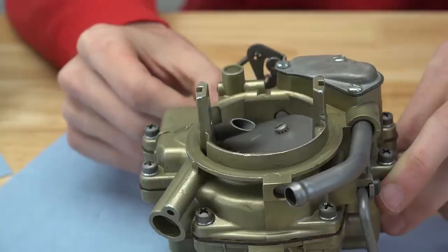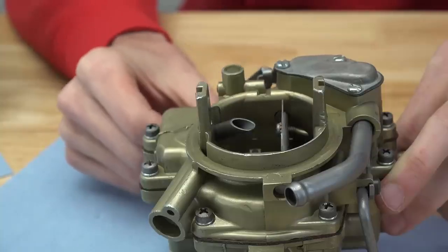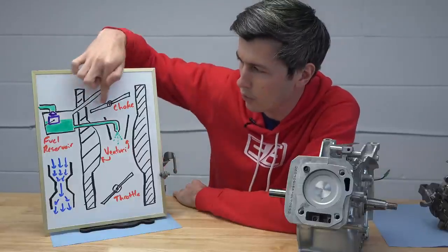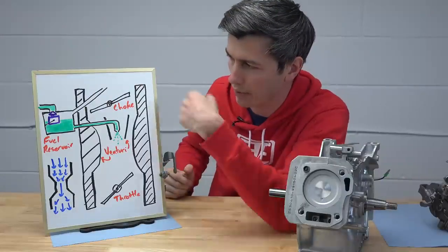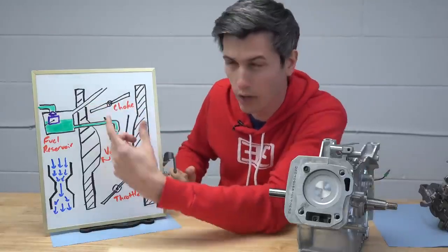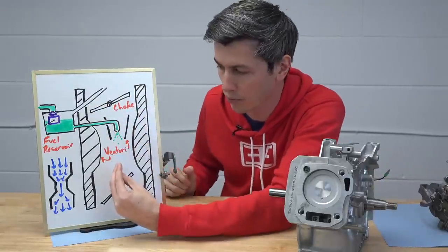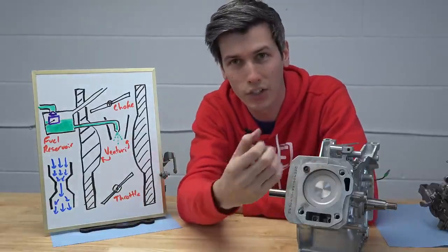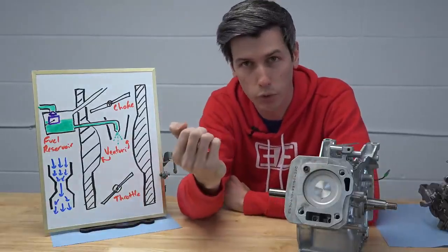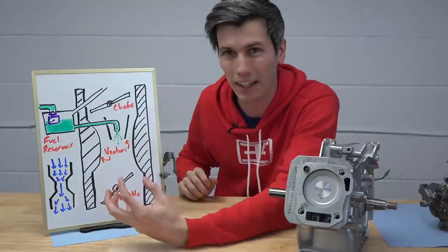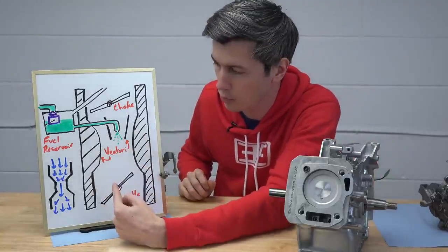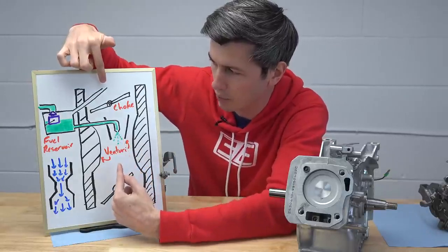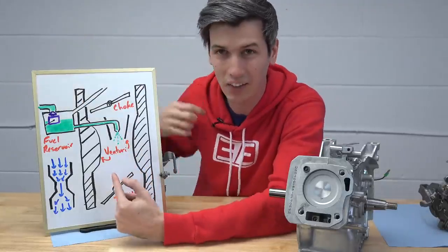On the entrance side of the carburetor, there's another valve, the choke, which is used for cold starts. So the choke is used to close off the entrance to your carburetor. By closing off that entrance, you create a really strong vacuum within the carburetor when you're trying to start the car. Because the engine is pulling the piston down, it's trying to pull in air and fuel, and in doing so it creates a strong vacuum within this carburetor. And so you have a strong vacuum on one side, you've got atmospheric pressure on the other, so it dumps in a lot of fuel.